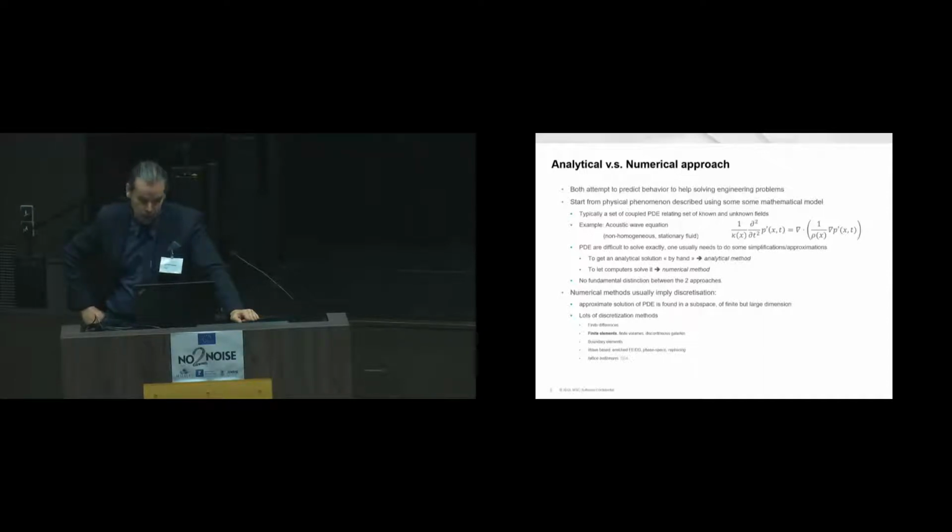Boundary elements were used a lot for exterior acoustic problems because they do not suffer from the difficulty of discretizing an infinite medium. But they are a little bit less used now for some reasons I will explain later. And you have wave-based methods, where you can start to enrich finite element methods with some wave solutions, and then you go to solutions that do not solve directly the same equations as the PDE itself, but do some ray tracing, like some high frequency approximation, a little bit like optics.